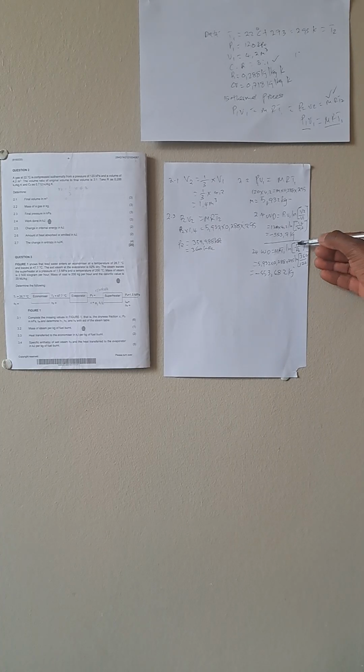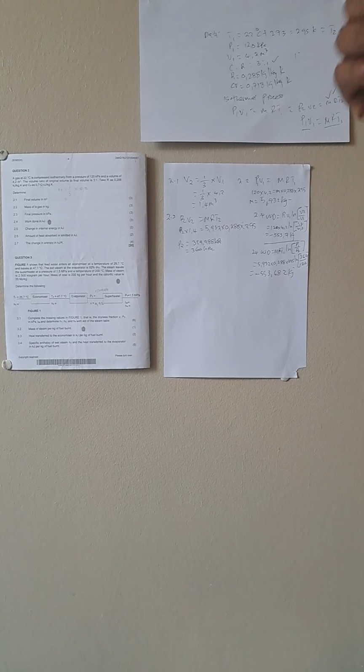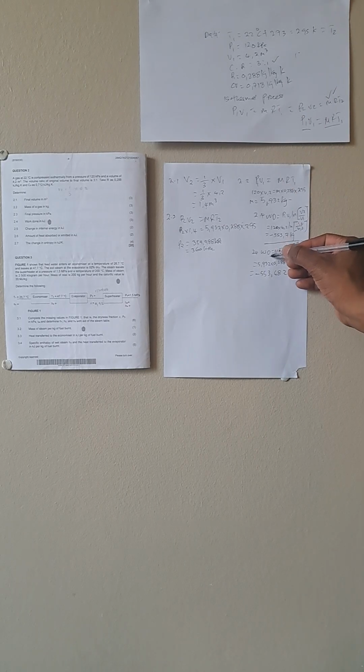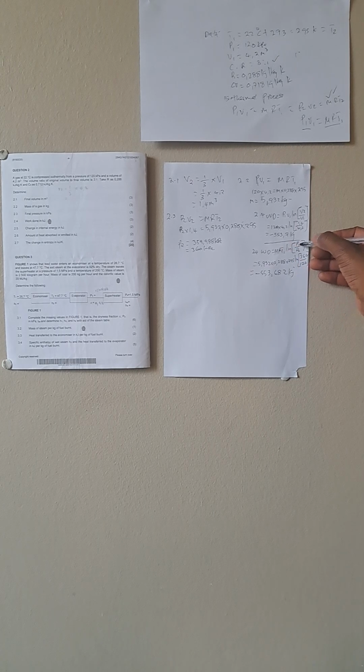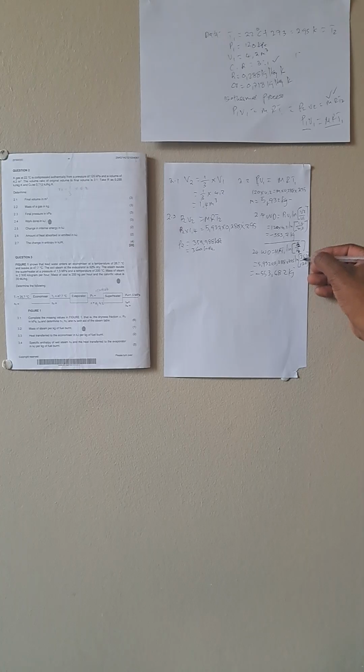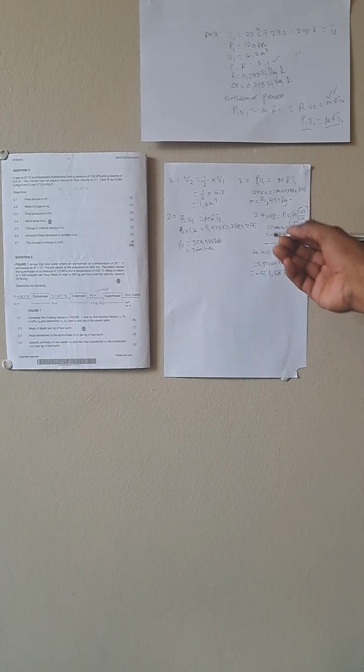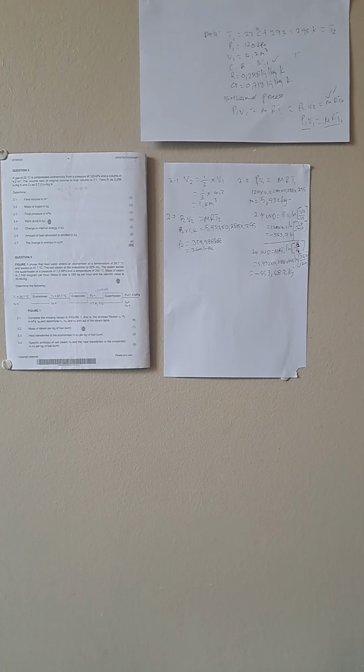Yeah, but there is a small error that I think we made on our formula here. Can you check on your formula? Work done equals MRT1 ln, rather it has to be P2 over P1. Yes, it has to be P2 over P1. In other words, you just do the opposite so that our answer remains with the same sign. If you do the inverse, it will give you a positive sign. So we need to be consistent. We need to get our negative answer at that point.